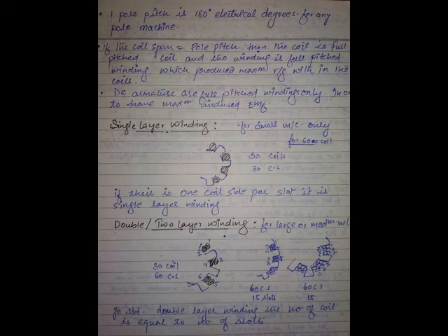Winding is nothing but conductors made into turns, turns made into coils, all in series. Means the current flowing in a turn and the current flowing in a conductor are the same. Is the point clear? Don't think the armature current means only the current coming into the load. Yes, you are right, it is the current flowing to the load, but the current is flowing through each conductor.